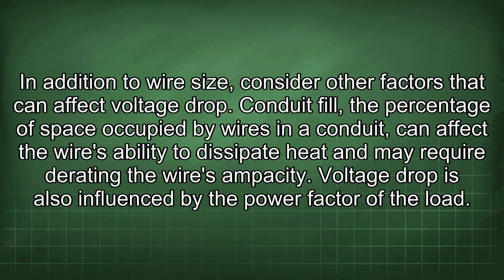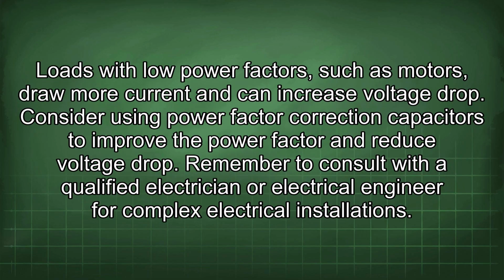In addition to wire size, consider other factors that can affect voltage drop. Conduit fill. The percentage of space occupied by wires in a conduit can affect the wire's ability to dissipate heat and may require derating the wire's ampacity. Voltage drop is also influenced by the power factor of the load. Loads with low power factors, such as motors, draw more current and can increase voltage drop. Consider using power factor correction capacitors to improve the power factor and reduce voltage drop.